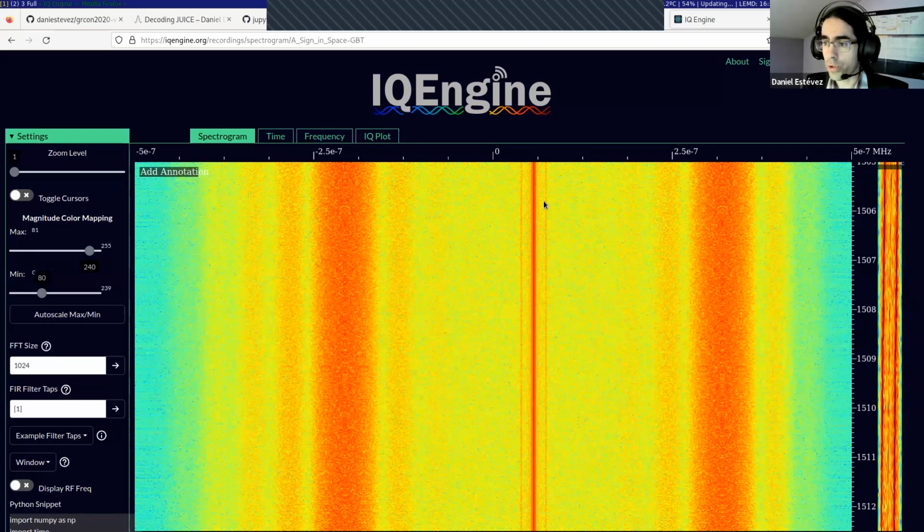So that's what this is used for: phase synchronization with the transmitter. Since this is an X-band signal, which goes out at 8.4 gigahertz, synchronizing to the signal means achieving a time synchronization of approximately 10 picoseconds. And 10 picoseconds is really precise. So that's the reason we have a dedicated carrier for that.